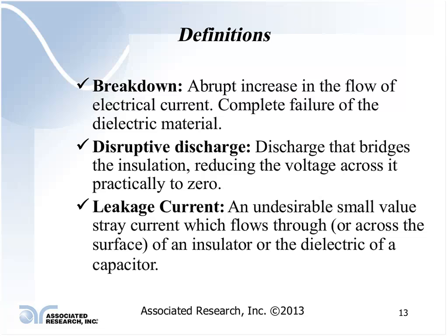Most of the time the minimum interval is annual for calibration on the equipment, but they also want you to do a daily fail verification. And what is the purpose of that? The daily fail verification is there to give you some reference point that you know for a fact that you have tested your instrument that is doing this test to verify that it will detect a failure.